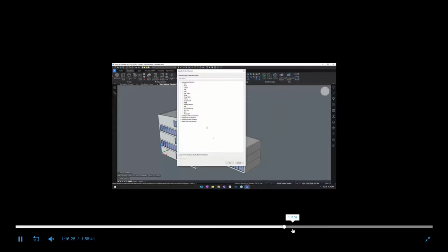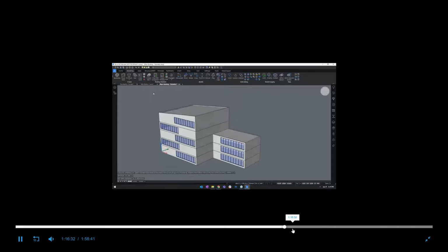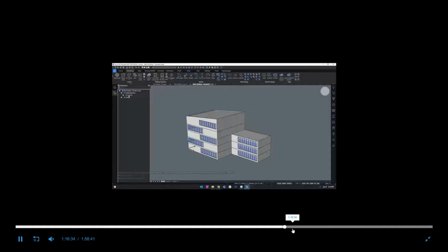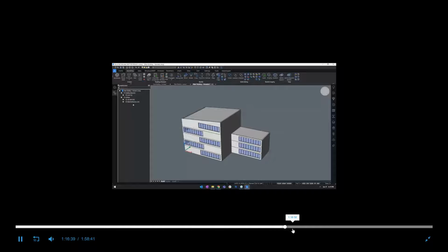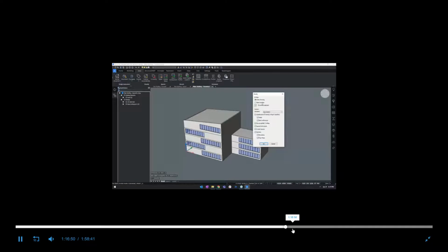Don mentioned the Bimify workflow earlier. I will show you what it does now. Basically, it will classify objects for us, solids and block references. It will recognize structural and MEP profiles. It will find spatial information in our model and define some spatial objects, and so on. I generally recommend showing this process live because it's very powerful. It doesn't really matter which model you use.